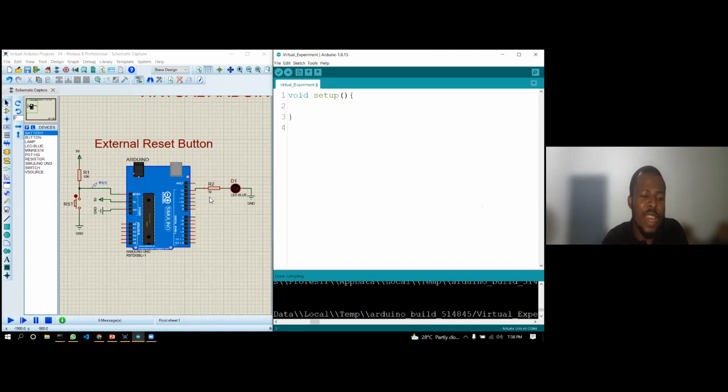So we have to find a way of limiting it and also dealing with the extra voltage so that if, for instance, we are saying that 3 volts should drop across this blue LED, that means that we have an excess 2 volts to throw away. That is what we need this resistor for, to handle that excess so that this doesn't burn out. So in essence, this resistor is serving as a protective or shield resistor, dealing with the excess voltage.